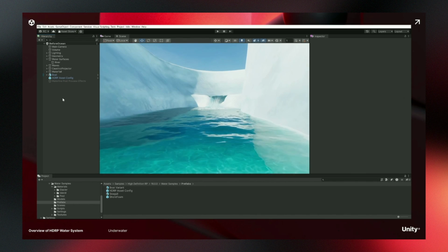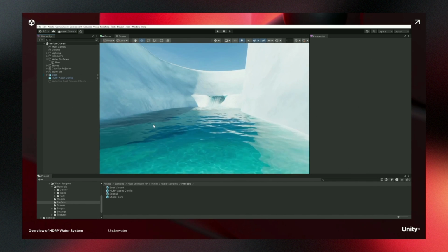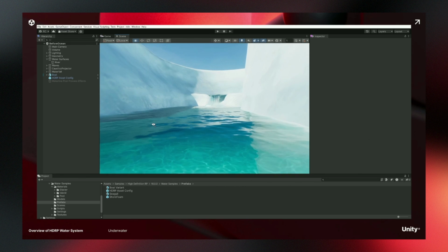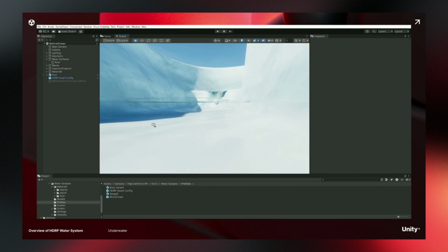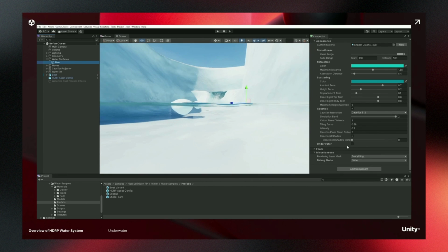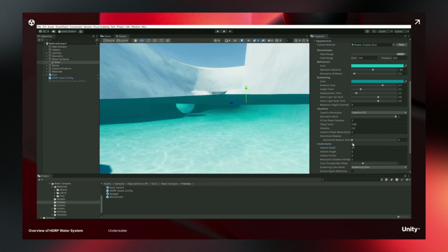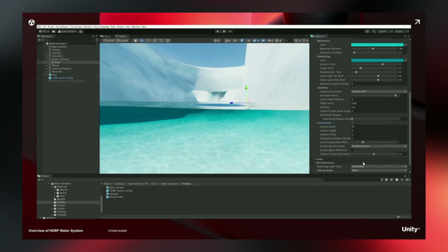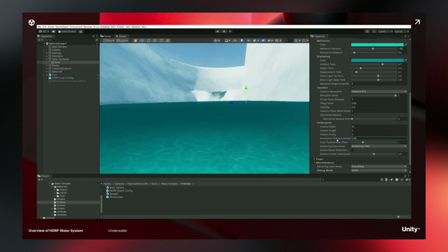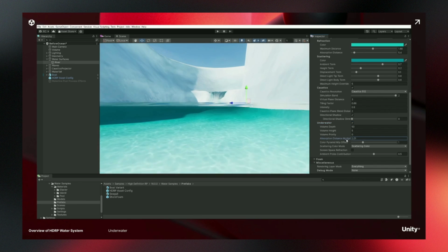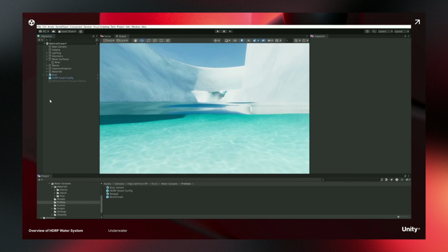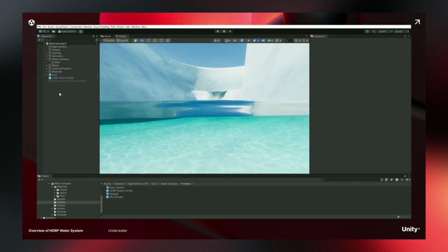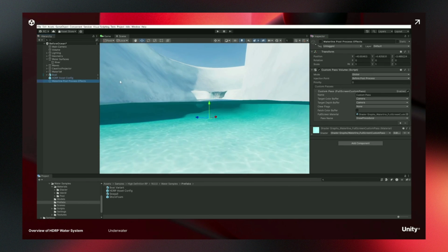And last but not least, now that we saw the tip of the iceberg, we're going to try and dive in and see the immersed part. So we're going to start by enabling underwater on our water surface. And when you enable that, you enable HDRP to still render caustics, absorption, and refraction when it is underwater. When the camera is at the limit, below and above the water surface, HDRP renders what we call a water line, so that's the line we saw here.